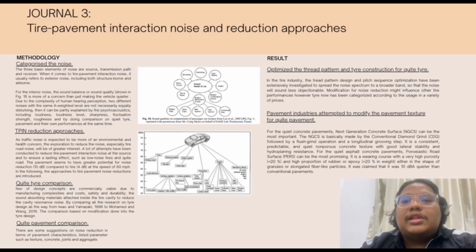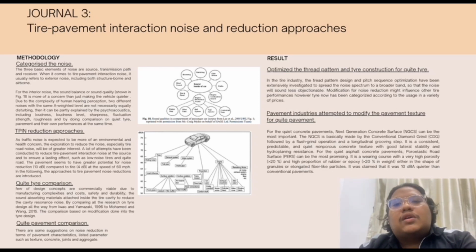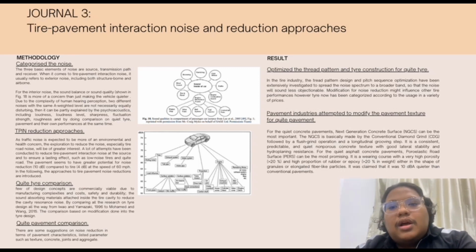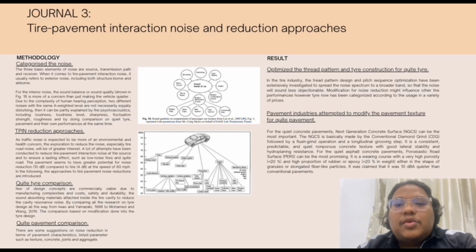First, the quiet tire comparison. Few of the design concepts are commercially viable due to the manufacturing complexities and costs, and safety and durability. Sound absorbing material is attached inside the tire cavity to reduce the cavity resonant noise. By comparing all the research on tire design, all the way from Iwao and Yamazaki 1996 to Muhammad and Wang 2015, the comparison is based on modification done to the tire design.